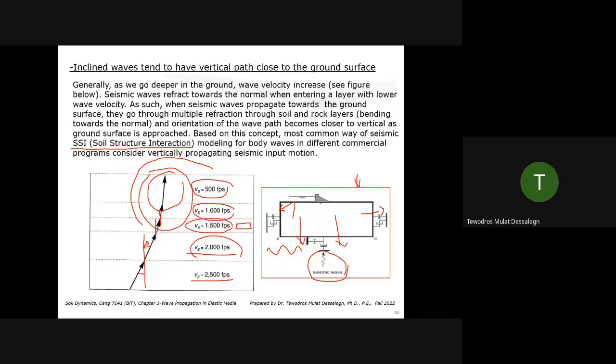A wave entering is being spread out. When it reflects back from the ground surface, it's being spread out. Because of that spreading, indirectly, you included radiation damping by creating a 3D model. By creating a larger area over here, you are actually introducing a way for the wave to get weaker because it's spread out in a larger area.